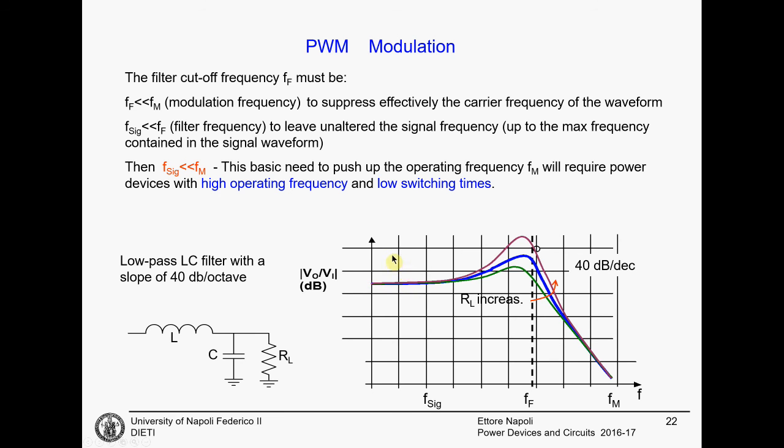A note on the pulse width modulation and filtering, because we need to design the LC tank, that is the filtering section of the class D amplifier, in order to keep the signal and remove the modulation frequencies. Let us name f the filter cutoff frequency.